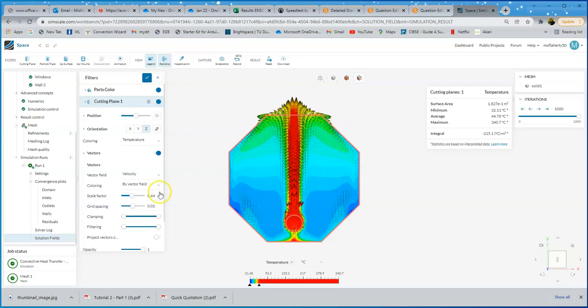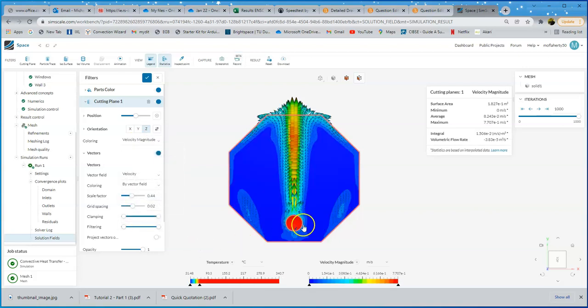If we color that according to velocity next, instead of velocity, put velocity here and magnitude. You can see that we get a maximum velocity of about 0.7 meters per second. So this is natural convection, so we're not going to get high-speed velocities. Here, it's being driven purely by buoyancy, by heating of the air and reducing its density. And so we get up to 0.7 meters per second, nearly a meter per second, about 2 or 3 kph, 3 or 4 kph in fact.